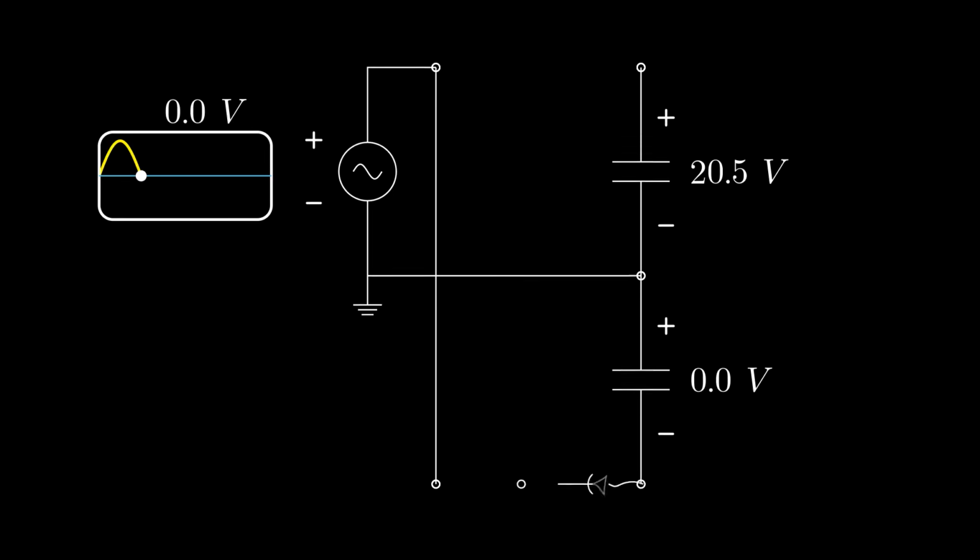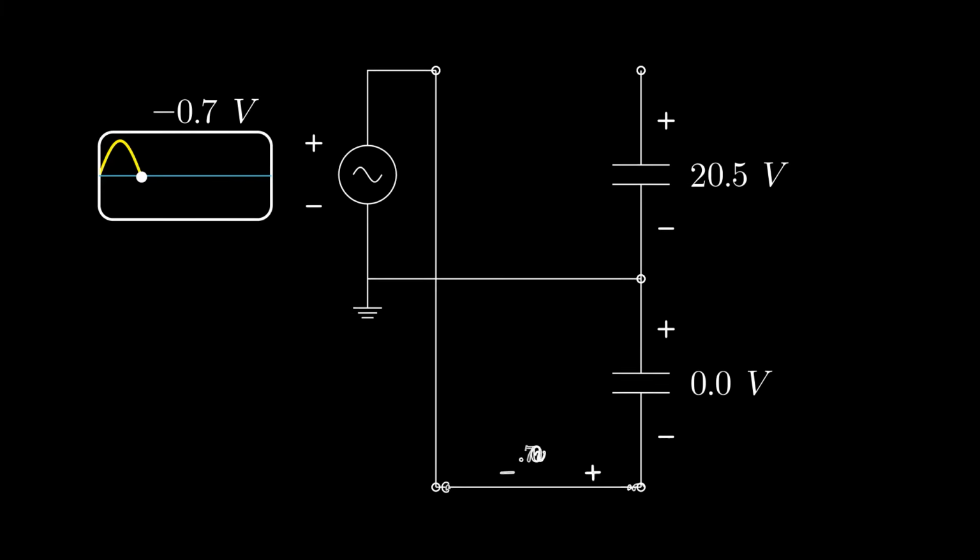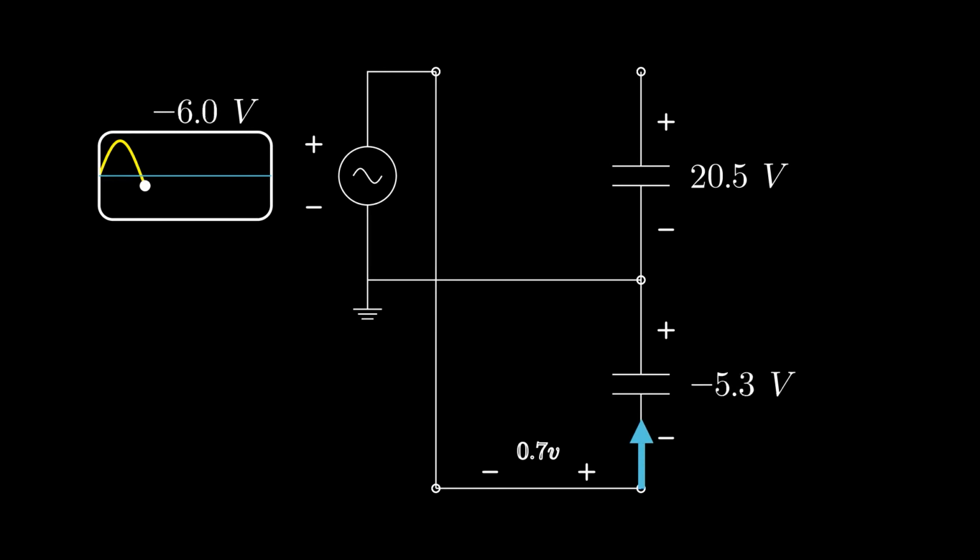Once we've swung back to 0 volts, the bottom diode is still off because we need to go 0.7 volts below the capacitor voltage. Once we have done that, this negative current will now flow through the capacitor, charging it to the supply voltage minus 1 diode drop, but this time negatively relative to ground. We can now see why this is a full wave voltage doubler.